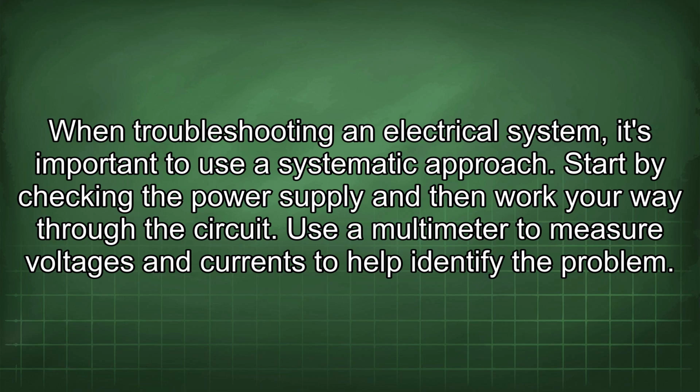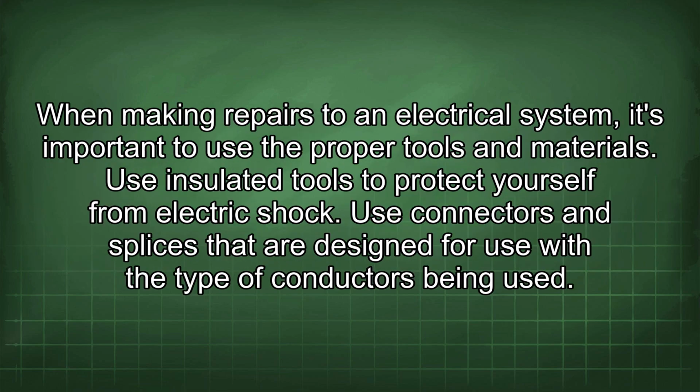Start by checking the power supply and then work your way through the circuit. Use a multimeter to measure voltages and currents to help identify the problem. When making repairs to an electrical system, it's important to use the proper tools and materials.